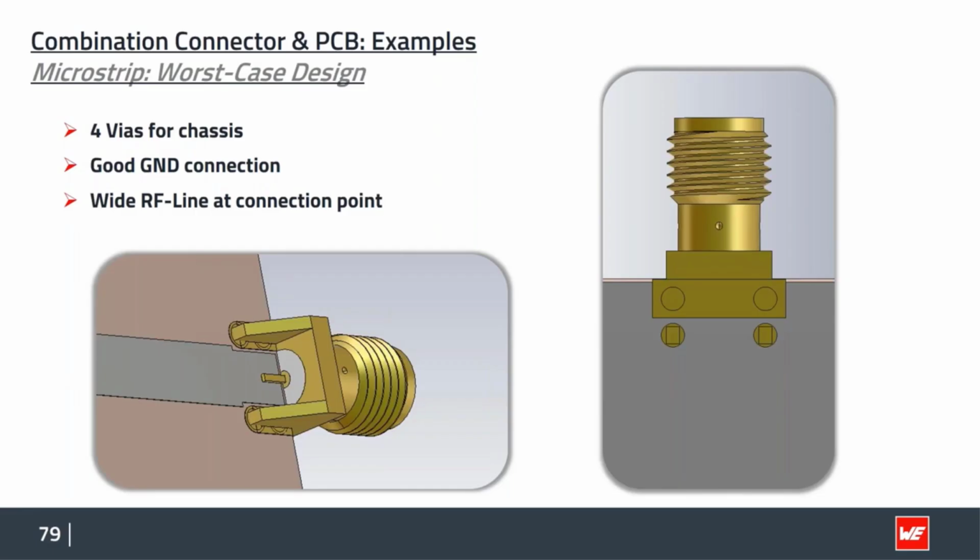But now it really behaves like a coplanar waveguide, and this means that the gap width here, left and right, has a lot of influence or defines how wide our PCB strip here in this area must be to fit to the 50 ohm of impedance. And this is what we did not correct. We just left it as it was and just changed or optimized the ground here. And this is the reason why we have now this huge mismatch directly here in the interface part.